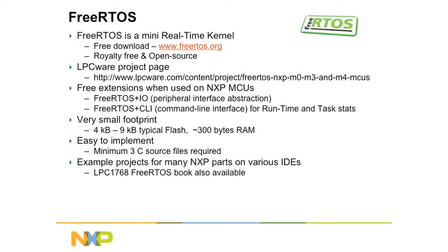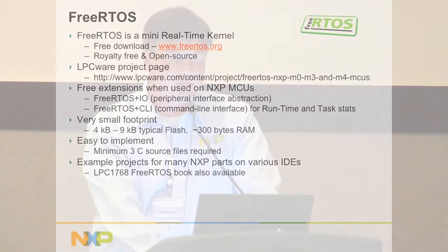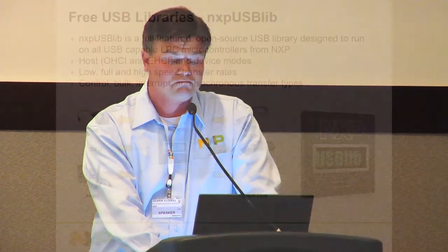And there's also some free extensions. These are extensions that you usually have to pay for, but you get for free when you're using them with NXP MCUs, such as the peripheral interface abstraction and the command line interface to control runtime tasks. All of that, lpcware.com, once again, that's where you get everything. It's very easy to implement. There's 3 files, you add those to your project, and that sets up the RTOS, and then you have a scheduler running that you can start spinning off threads on. Many example projects are available for various IDEs, and there is a book about FreeRTOS that is basically based on the LPC1768 part that we have that you might want to check out as well.